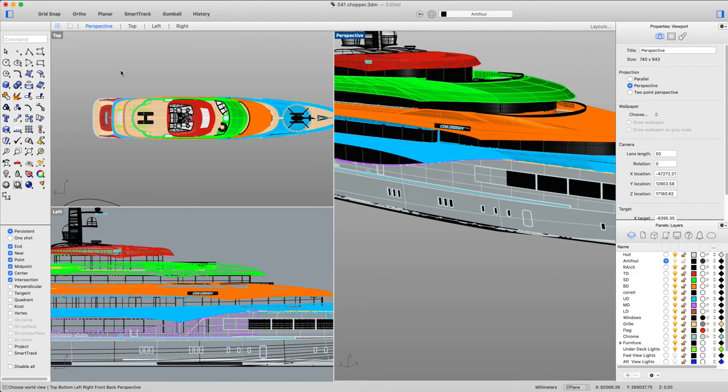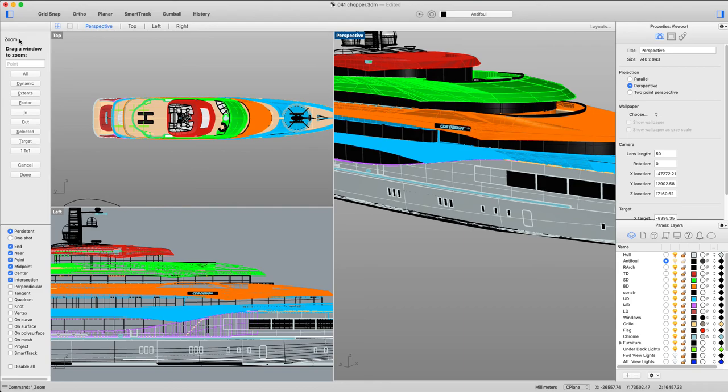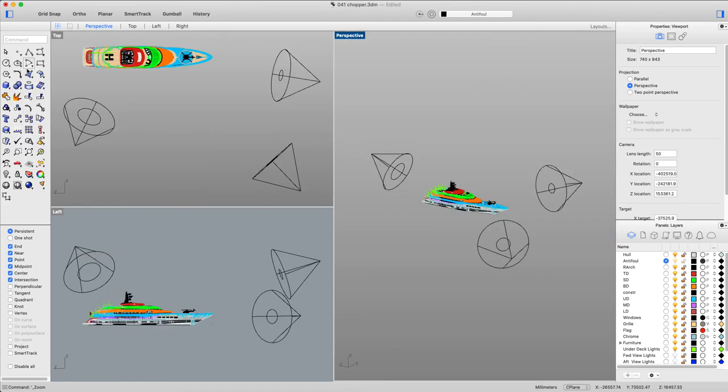One of the commonest shortcuts that I will use is, I'll just write it here, ZAE, not zoom naked. Hitting Z first, then hitting A for all, and then either this one or this one. So E takes you out to the edges of the drawing, right?